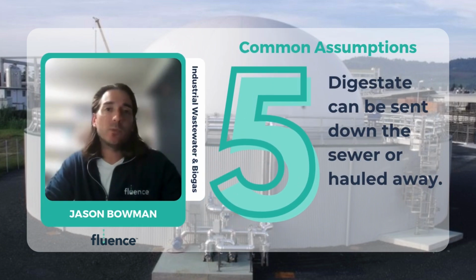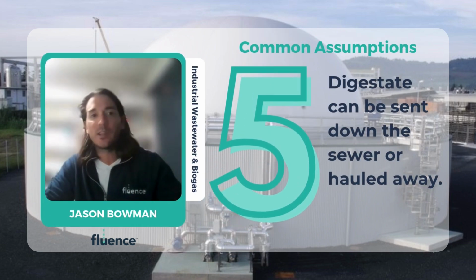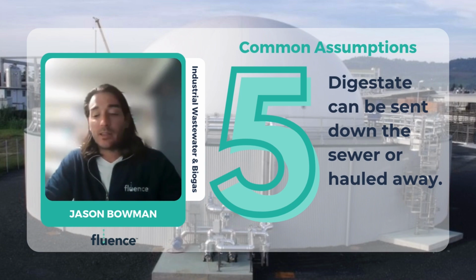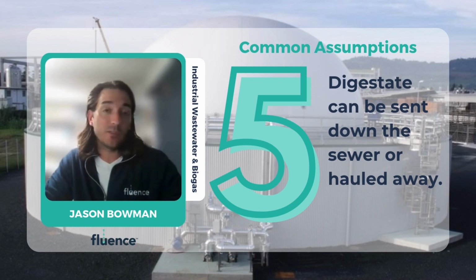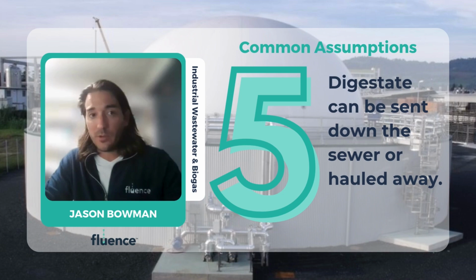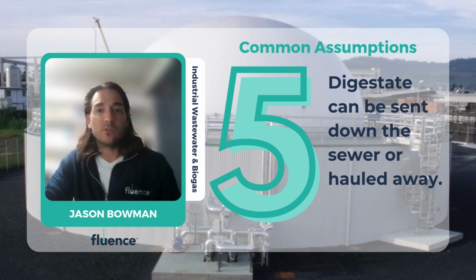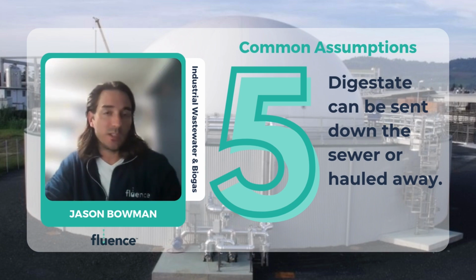And last but not least, we have assumption number 5, and that is that, hey, I can just send my digestate to POTW untreated. That is, I can put the digestate down the sewer line. First and foremost, it's highly unlikely any municipality is going to agree to that just because of the simple fact that you're going to overload their system. So for the sake of argument, let's try to put this into perspective. Let's use a regional food waste digester facility. The digestate COD value is 13,000 milligrams per liter. The ammonium value is 2,000 milligrams per liter.